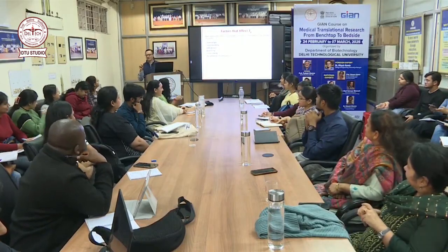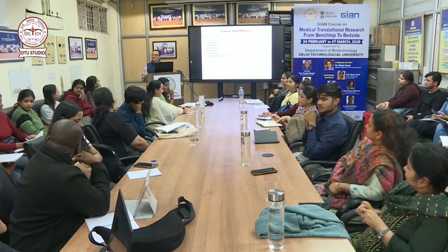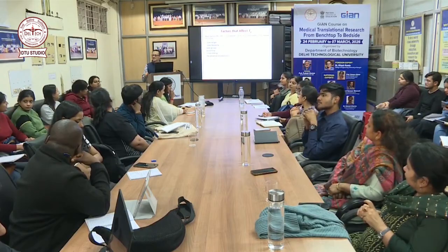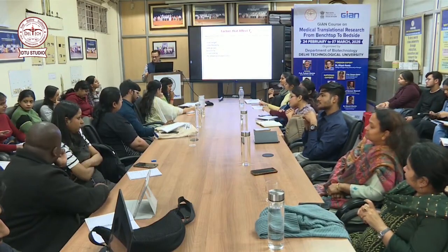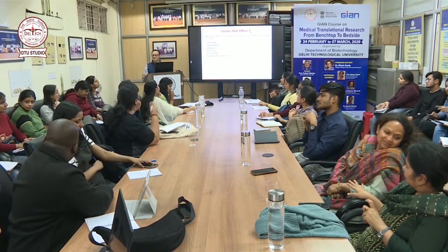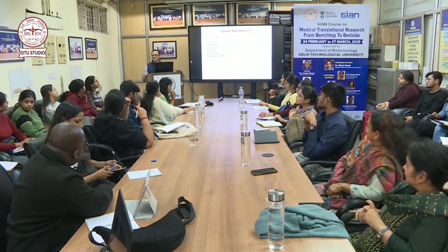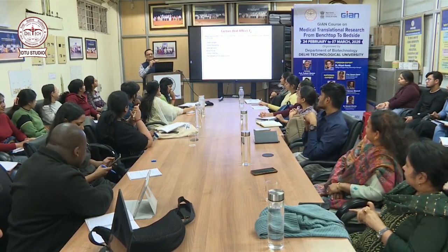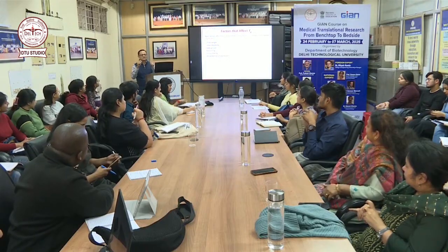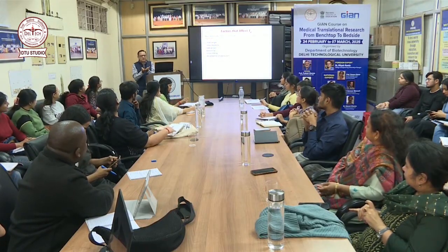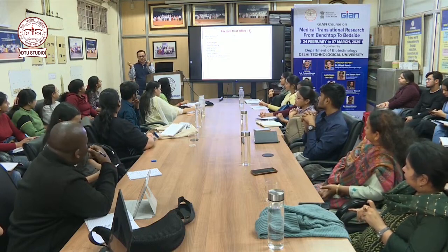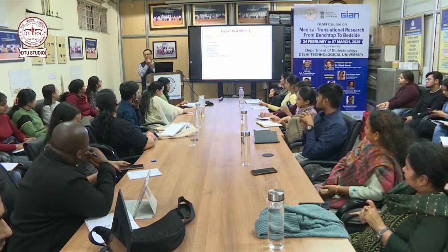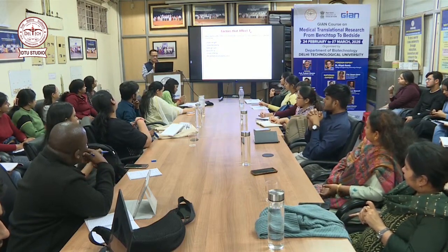Can you explain why? As you said, above Tg our material is rubbery, right? So if chain length is increasing, it is becoming more difficult. You need to provide more heat for it to become softer, right? So temperature is going up, Tg is going up.